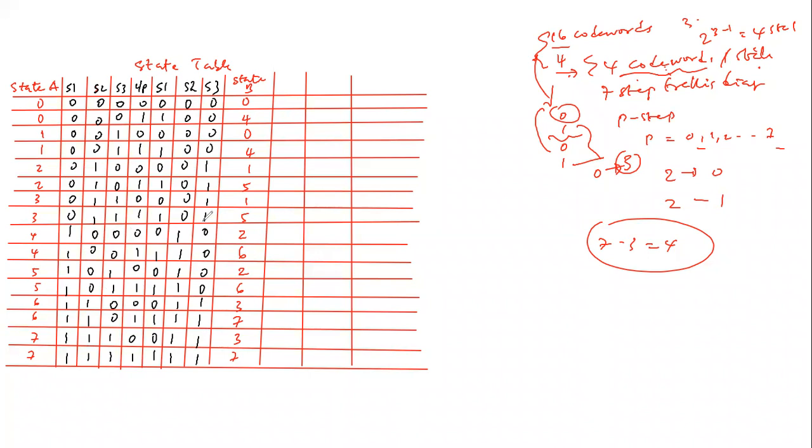Now, you'll recall that we have output bit 1, output bit 2, and output bit 3. Output bit 1 is the same as shift register 1 plus shift register 2, then output bit 2 is the same as shift register 2 plus shift register 3, while output bit 3 is the same as shift register 1 plus shift register 3. So once we begin to play with these, this leads to our new state.